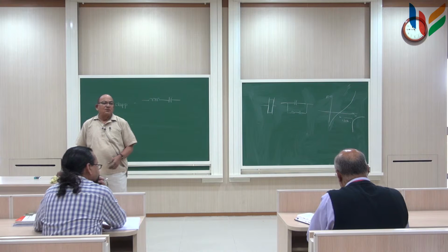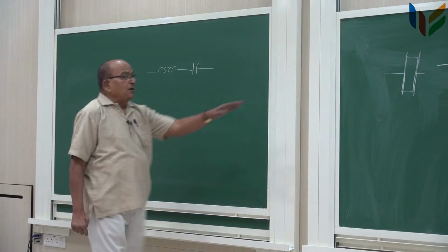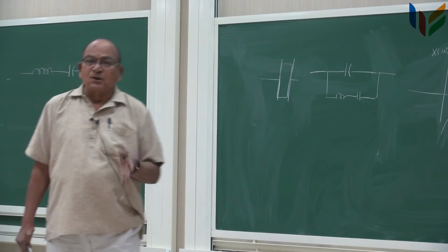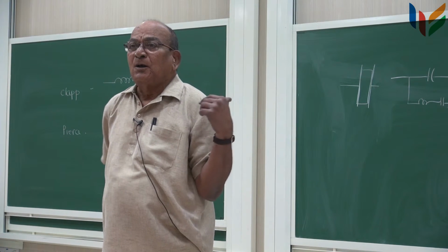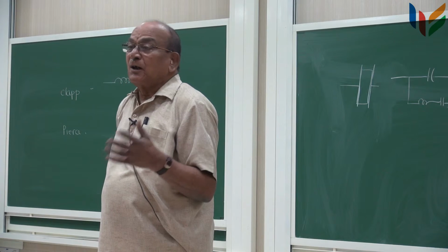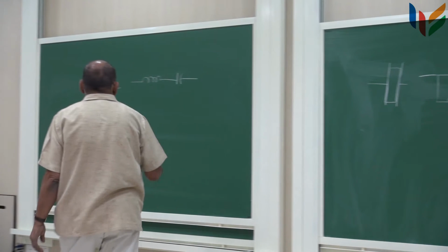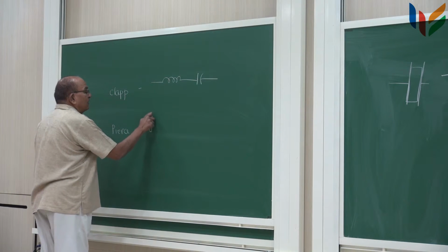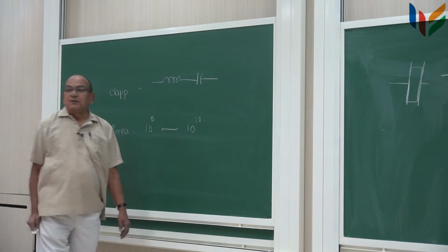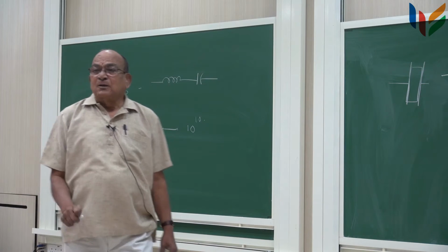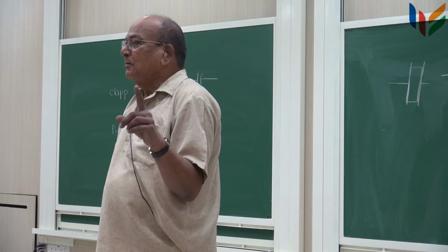using a crystal. And the frequency stability you can get in a Pierce oscillator using a quartz crystal, depending upon of course the quartz crystal, but any commercial quartz crystal made for this purpose will give you frequency stability of the order of 1 in 10 to the power of 8 typically. And with some effort I can even push it to 1 in 10 to the power of 10. What it means is it loses or gains one cycle over 10 to the power of 8 cycles.